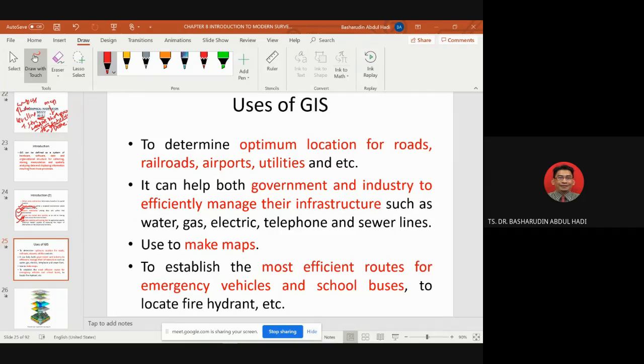We are not like in Korea or America, where they put all the water, gas, electricity, telephone, civil lines, internet, everything, in one sewerage, in one tunnel. This tunnel is made of precast concrete, and it's very big. They manage it and share it with all the water pipes, gas pipes, electricity cables, telephone cables, and sewerage lines. Because Malaysia is still moving toward that process, you must be careful and check with the agency before you do the excavation.